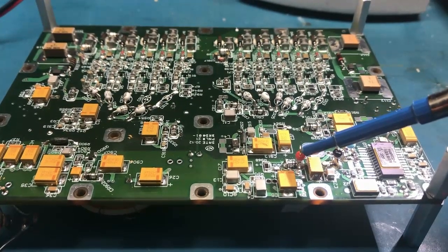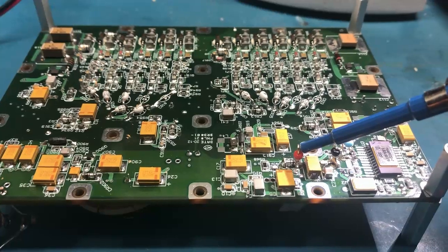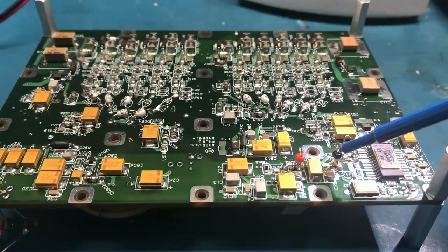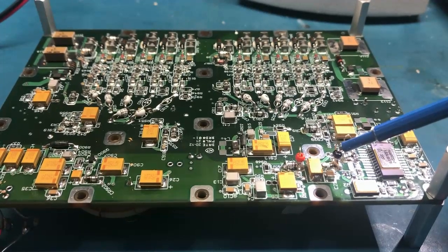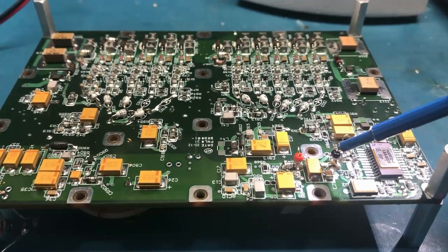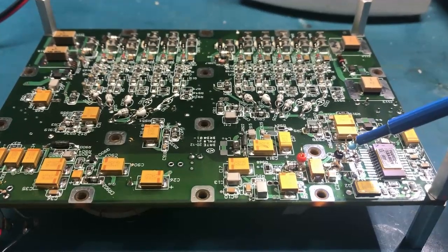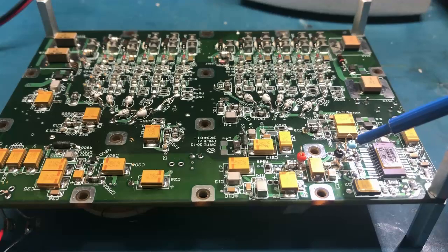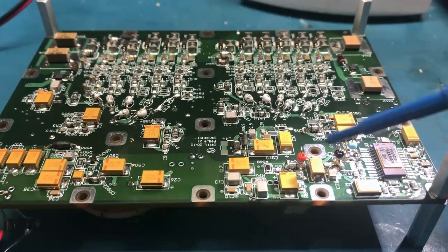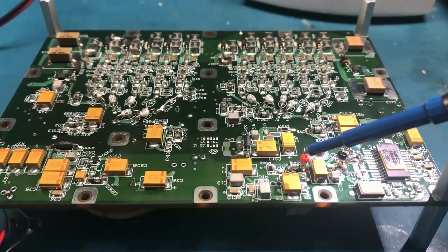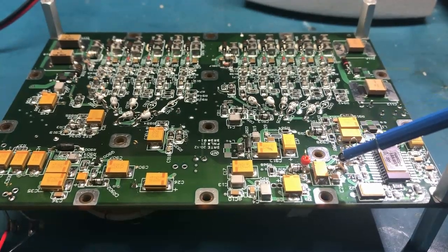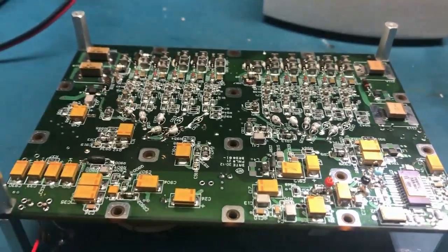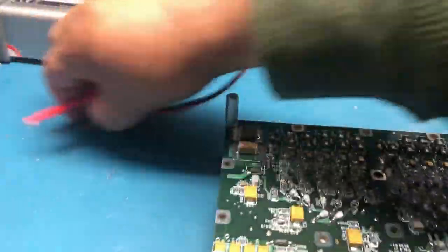This is the red, that's the high side of the injection resistor, and then this black test point is the low side of the injection resistor, and then this blue is the comp pin of the PWM. So those are the three connections that we need. So the transformer goes connected across those two pins. So I'll connect that.